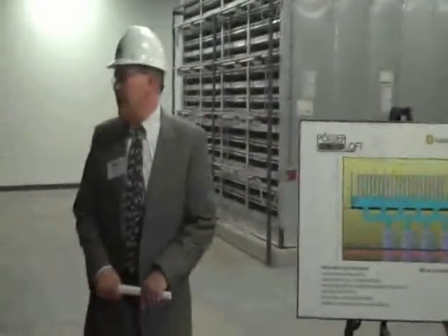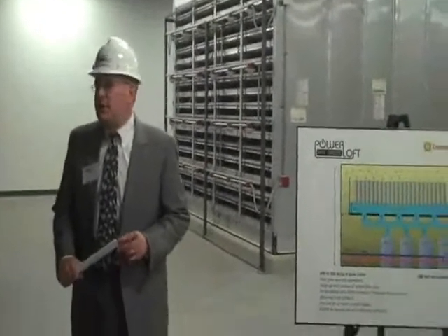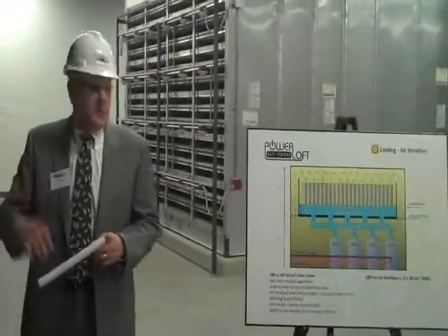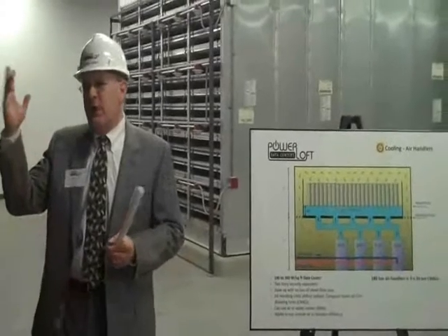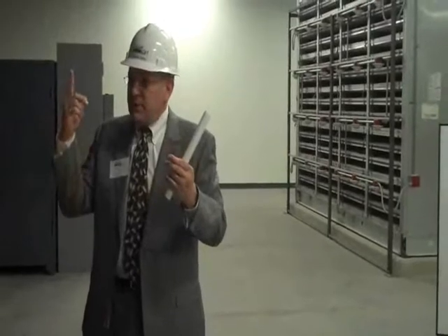The way we cool the building, unlike a legacy or traditional data center, this is a two-story data center. In a legacy data center, you would have computer room air conditioners on the floor with the racks and the servers. What happens there is what I'll call a law of diminishing returns. As it gets hotter upstairs, as you add more density to your servers, you have to start taking some of those racks out of that productive space and adding more computer room air conditioners. So you get a diminishing return.